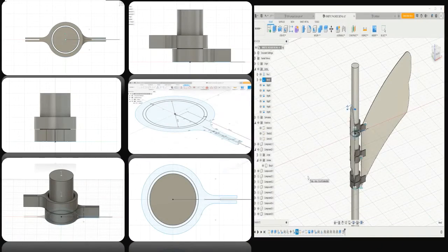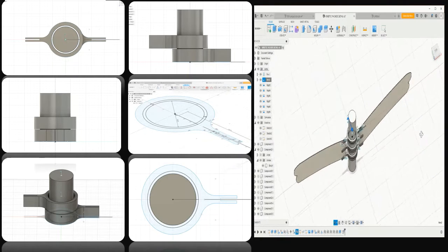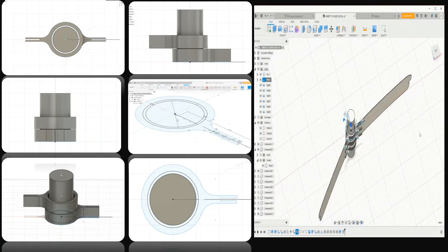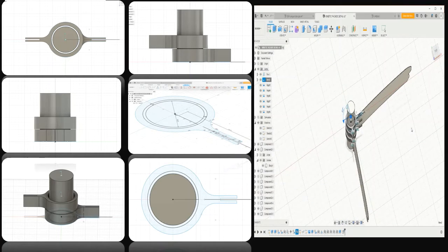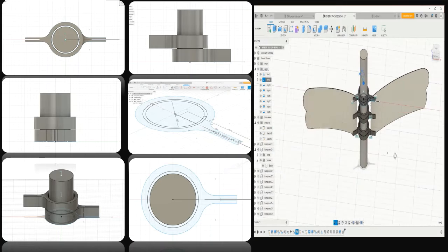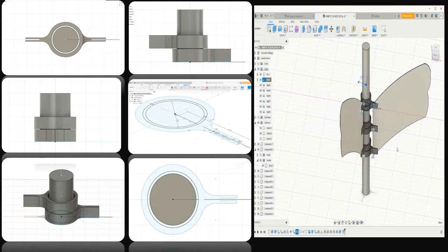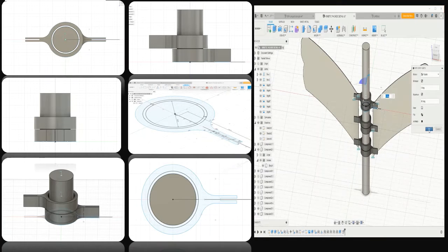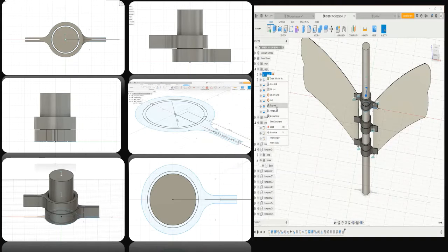Technically, the kinetic facade system could be applied by using 2 rotor elements, which are the wings and the stator around which the wings will be turning. The wing units are to be manufactured from a lightweight material which blocks solar radiations and allows natural daylight at the same time. However, the stator must be made of solid metal as it is the structural part of the system.